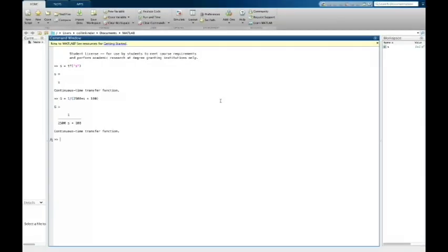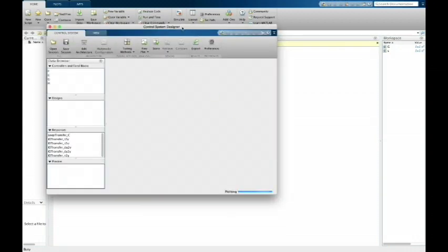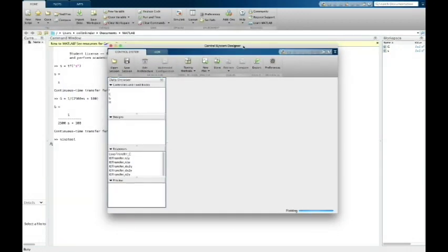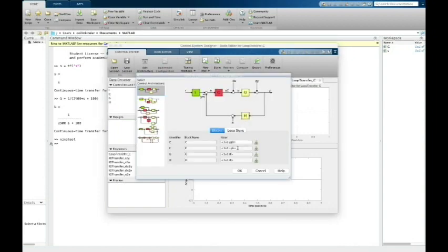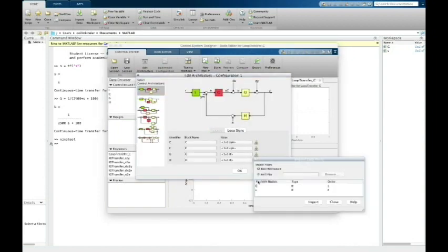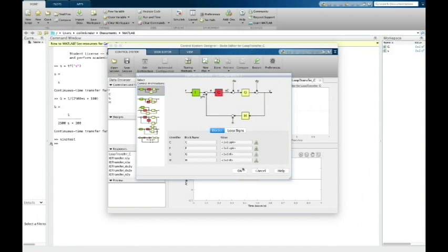We had originally done hand calculations on our system in order to determine what type of controller we should use, which was a PD controller, but found out that the constants we had determined actually made our system unstable. Thus, we turned to Simulink to analyze our system and make our controller much more robust and accurate. We began our Simulink analysis by plotting the root locus of our transfer function, G(s), and adding the time domain constraints determined earlier to the plot. This showed that our open loop pole did not fall within the acceptable region and our requirements were not met.